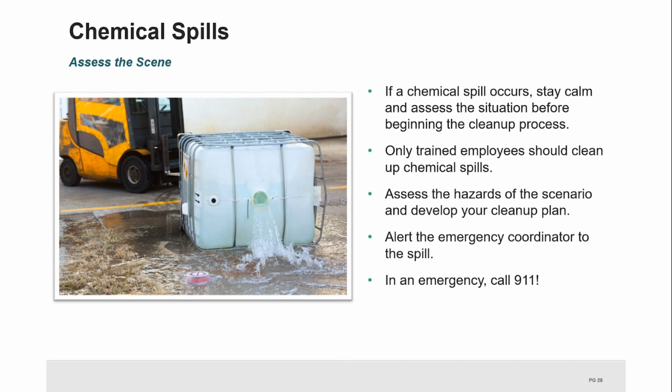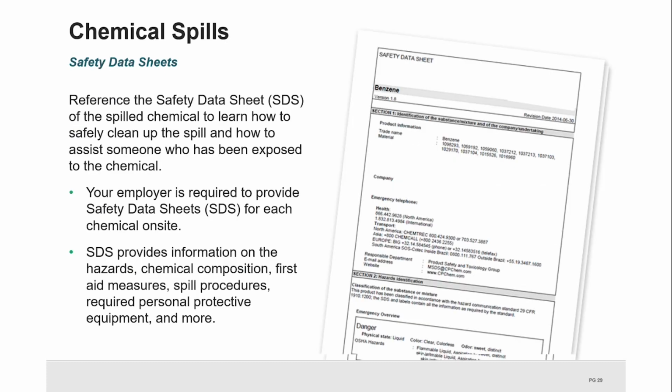You do not want competent or authorized people doing the cleanup. You want qualified, trained personnel that know the chemical, know what PPE to use, and what process it takes to clean it up. You do not want to put anybody in harm's way that's not trained to do so. I've already stated to base your EAP for that chemical spill off your safety data sheets. Any chemical, you can go through the manufacturer's online website and pull the SDS sheet for that chemical.